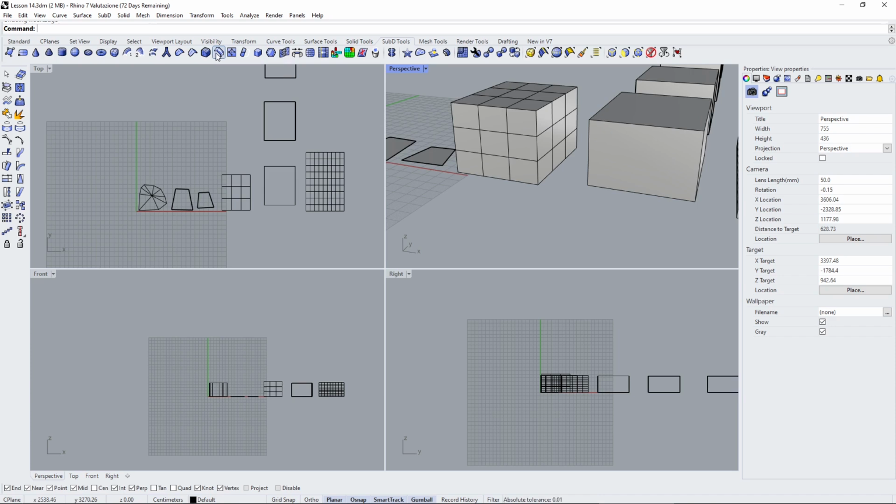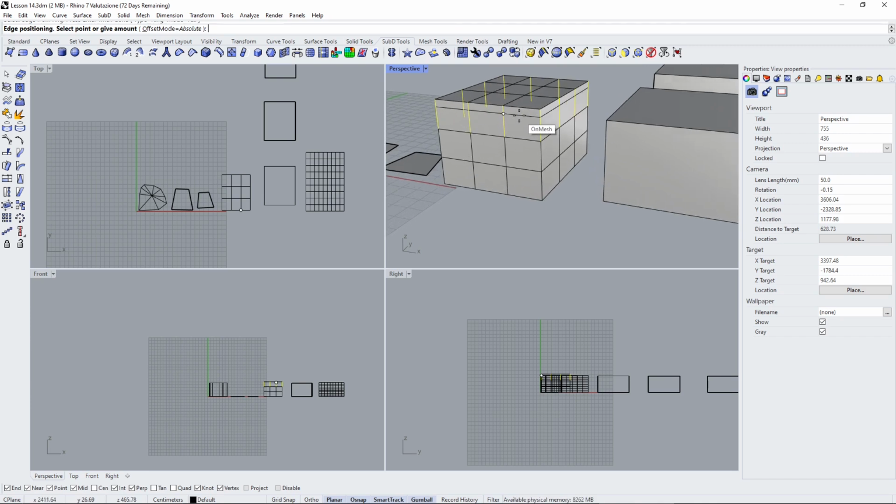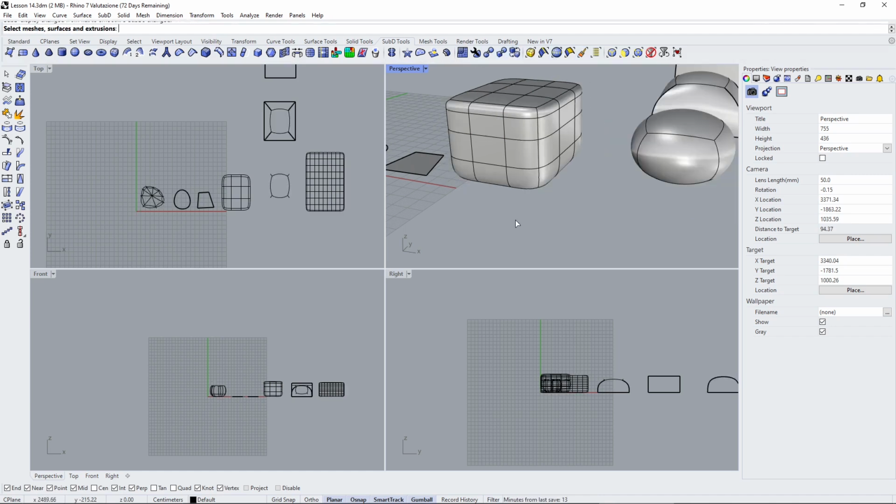You can do that also with the ring. So we have edge loop and edge ring. In this case, we are gonna select a ring like this, press enter, and I can place a line just right there near the corner, and that's gonna limit the roundness of that corner as well. And let's switch back to see the effect.